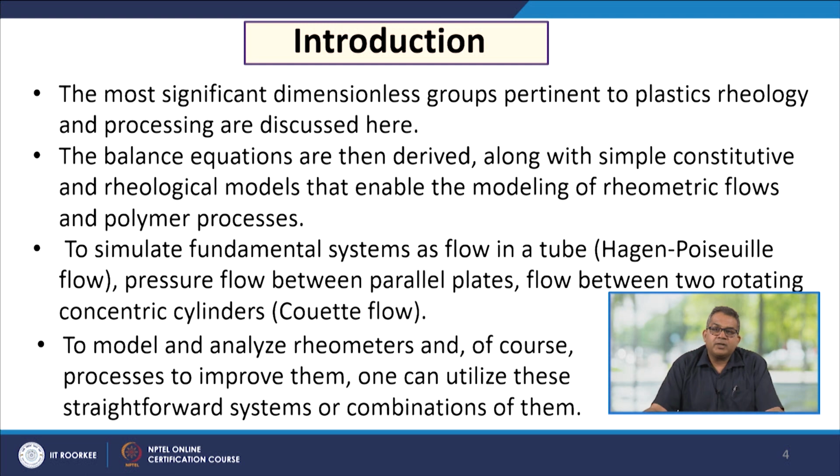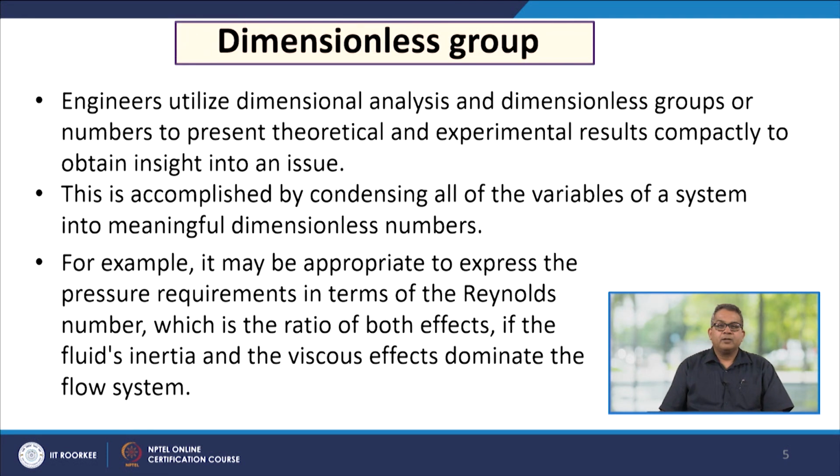To simulate the fundamental systems, such as flow in a tube, pressure flow between parallel plates, flow between two rotating concentric cylinders, and skewed flow, and to model and analyze the rheometer and of course the processes to improve them, one can utilize these straightforward systems or combinations of them. Engineers utilize dimensional analysis and dimensionless groups, and they are of very well-versed importance in all kinds of rheological studies. So, we are going to discuss the dimensionless groups.